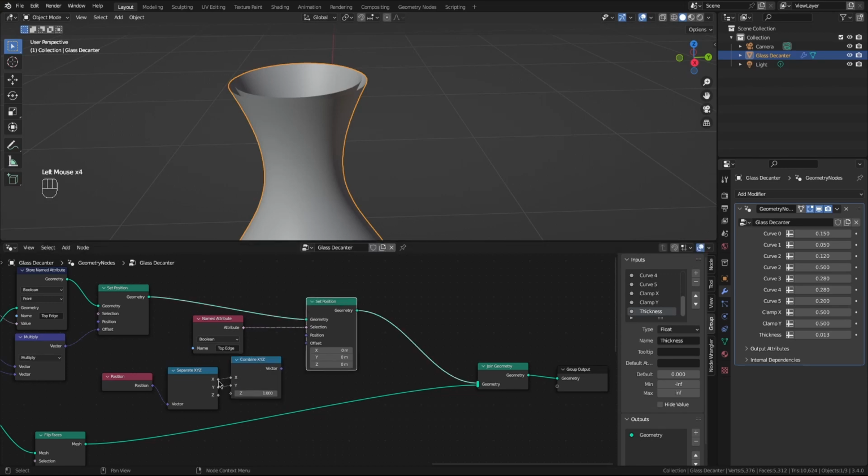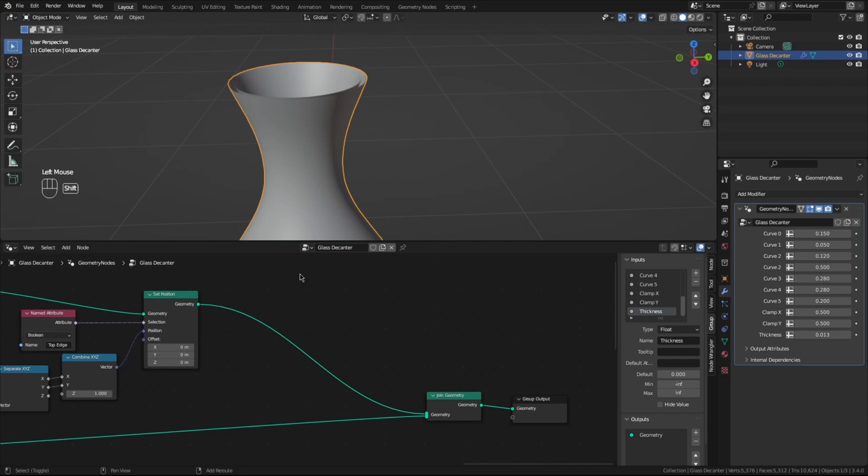So we'll take the X and Y of these labeled vertices unmodified, and the Z will be forced to be 1. And you can see it scooches up just a little bit, which is great. Now I want to create a new surface to join these two. So again, I'm going to take the points along the top edge of the inner surface and extrude them outwards. Once again, we're dealing with just the top edge, and this will be an extrude operation.